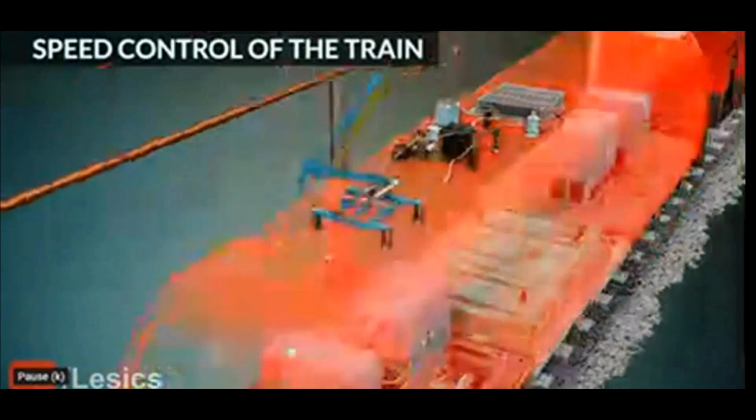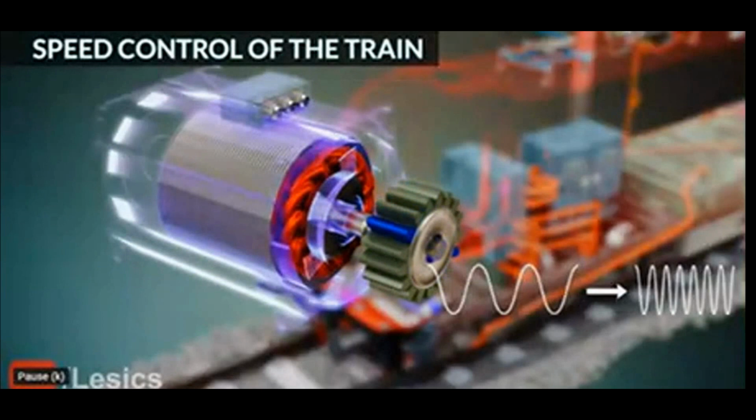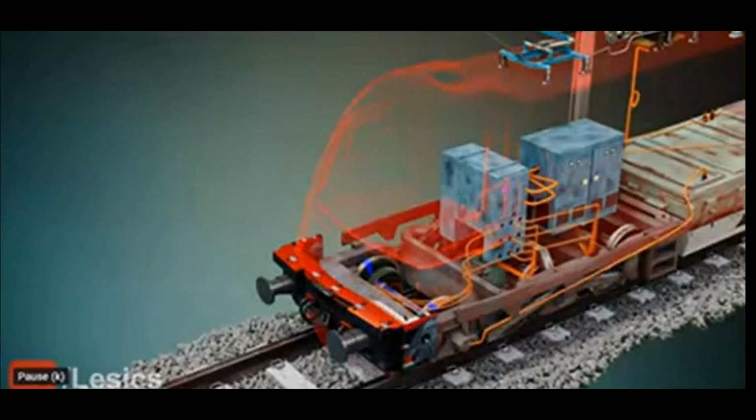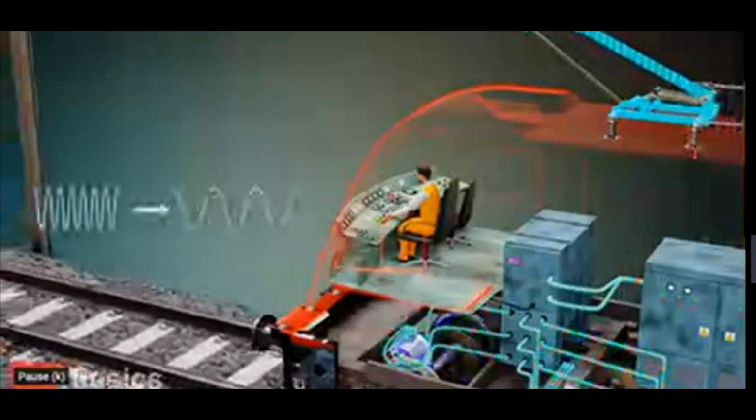We can control the speed by changing the induction motor power supply's frequency. This is accomplished by the rectifier and an inverter. The driver sets the lever onto a different notch to change the frequency and hence the motor's speed accordingly.